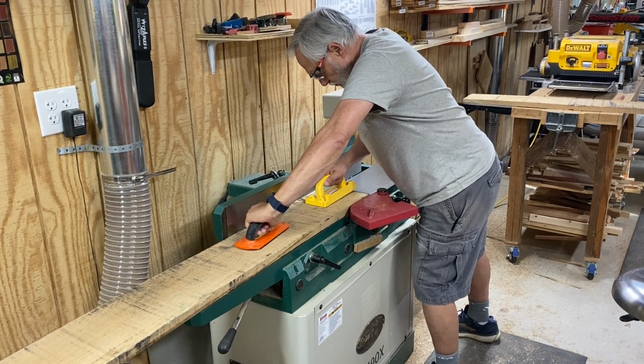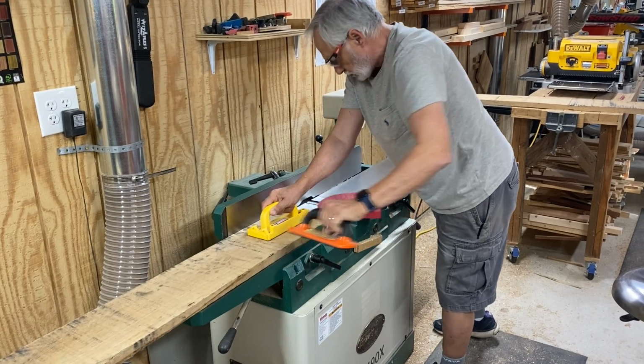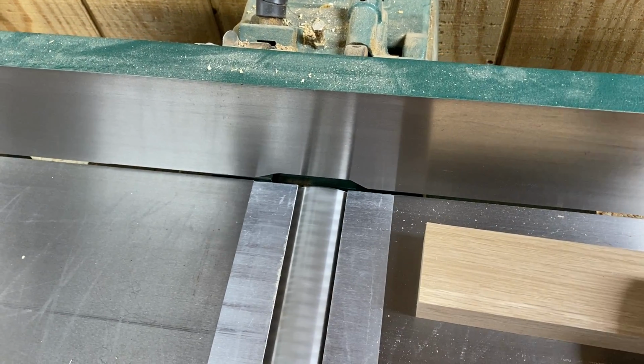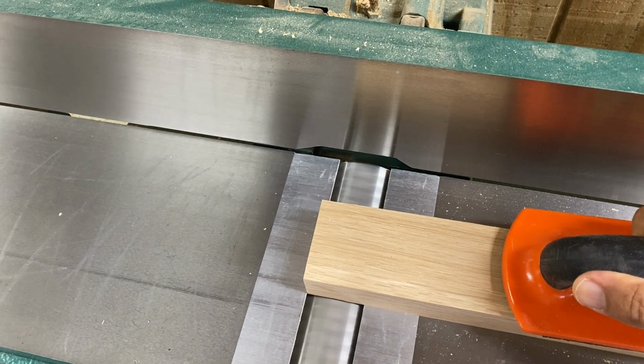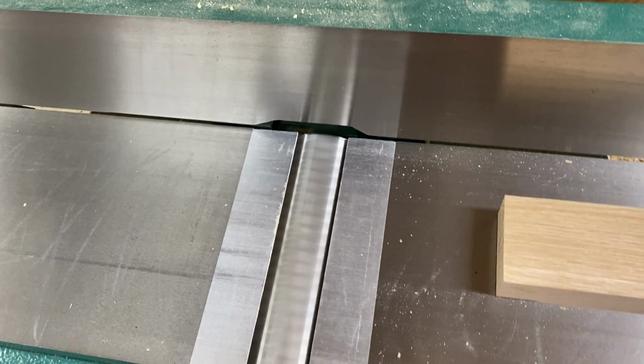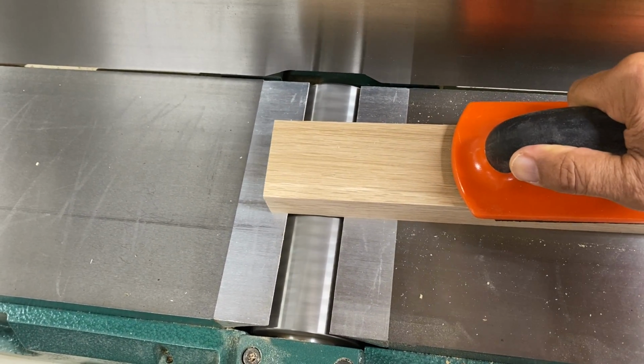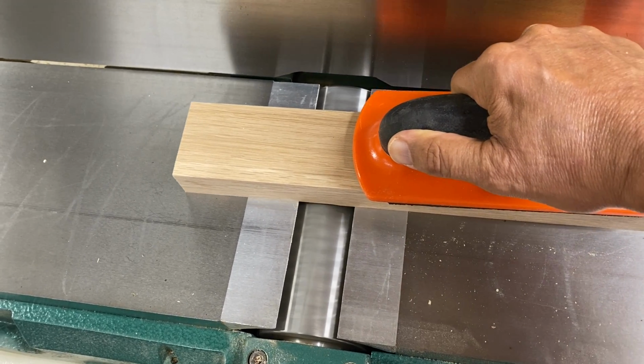A couple of points need to be made about how hard to push down. A lighter touch is preferred versus pressing down with a lot of your body weight. You can feel the board better with a lighter touch, and pressing too hard can actually take more wood off where you are pressing, especially on the leading edge where you press down hard to start the cut. If you find the leading edge of your board is getting caught on the edge of the outfeed table, but your jointer is set up properly, you're probably pressing down too hard. Lighten up and get more of a running start with your board and push it through to the outfeed table.